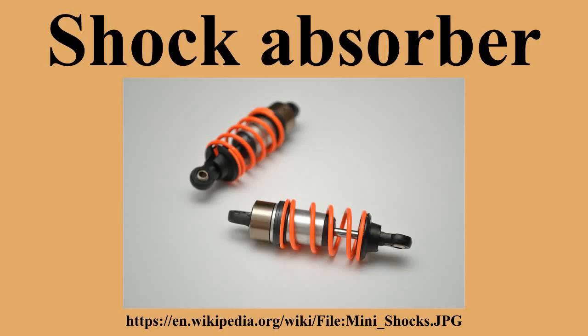Not only does this result in a complete disappearance of the comfort versus control trade-off, it also reduced pitch during vehicle braking and roll during turns. However, ASD shocks are usually only available as aftermarket changes to a vehicle and are only available from a limited